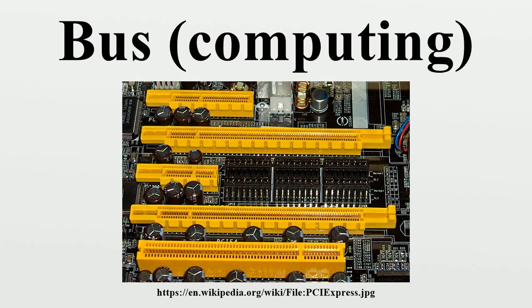In most traditional computer architectures, the CPU and main memory tend to be tightly coupled. A microprocessor conventionally is a single chip which has a number of electrical connections on its pins that can be used to select an address in the main memory and another set of pins to read and write the data stored at that location. In most cases, the CPU and memory share signaling characteristics and operate in synchrony. The bus connecting the CPU and memory is one of the defining characteristics of the system, and often referred to simply as the system bus.